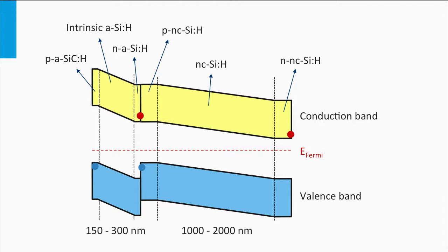Similar to the 3.5 multijunction, the electrons and holes have to recombine at the recombination tunnel junction between the n layer of the top cell and the p layer of the bottom cell. Often, a very thin and defect-rich layer acts like a tunnel recombination junction here. Here, these electrons and holes recombine. Again, the total current density is equal to that of the junction with the lowest current density. It means that in an optimized multi-junction cell, all current densities in the various subcells have to be matched to achieve the best spectral utilization.